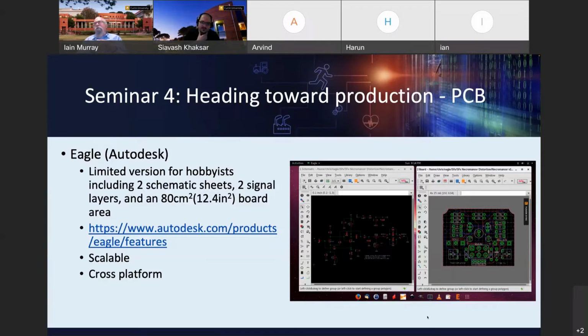Yeah, there's this one, and then there is another one, Easy EDA. I've sent a link to that in the chat. I think that one links with PCBWay, because PCBWay and JLC PCB have become pretty popular as PCB manufacturers in China. So they now have their own similar to Fritzing. But Easy EDA is also pretty good, and it also has a web version so you don't have to worry about operating system specs. Eagle is very good as well.